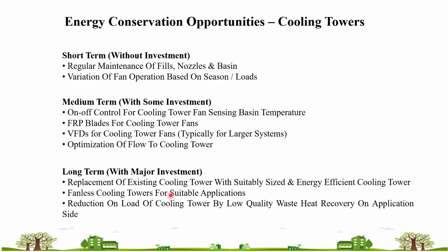Sir, I have one question. That fanless cooling tower, up to what capacity is it recommended? Is there any thumb rule? They are majorly recommended up to 400, 500 TR, not more than that. Okay.